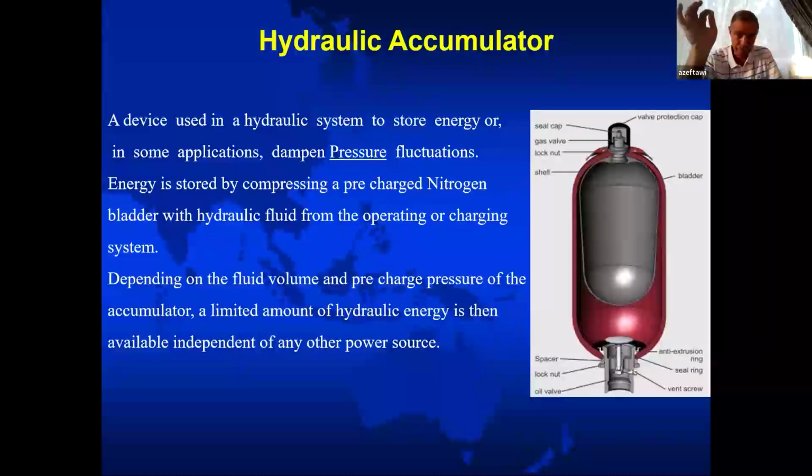During the job, when the power pack is running, when the engine is running, the pump is working. So the pump is always feeding the system with 1500 psi. If the power pack failed, the engine is not running, the pump is not working, so the pump will not feed you with 1500. So inside this accumulator, we have nitrogen at 1500 and the rest hydraulic oil at 1500.